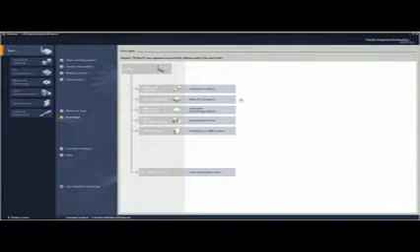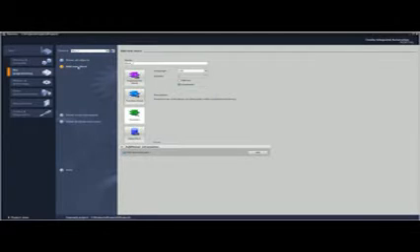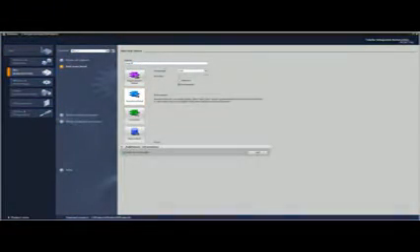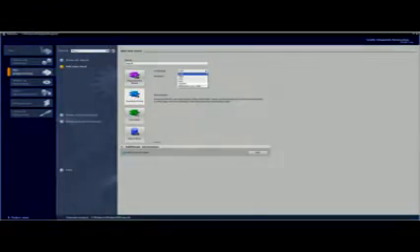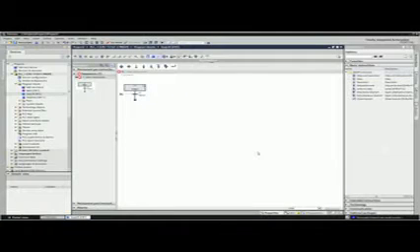How does that look in the TIA portal? In our example, 2 lifting units are to be controlled. To do so, first create a Graph function block in your project. You program the sequencers with a Graph editor.